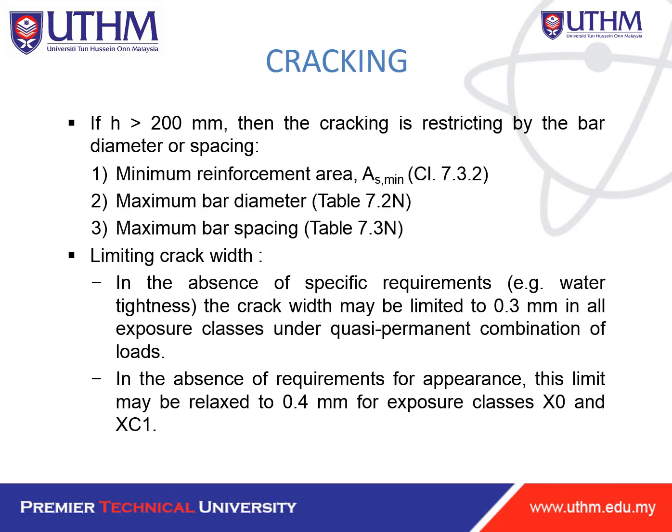If h is greater than 200 mm, then the cracking is restricted by the bar diameter or spacing. The minimum reinforcement area is according to this clause, the maximum bar diameter is according to 7.2 and the tables, and the maximum bar spacing is according to Table 7.3.